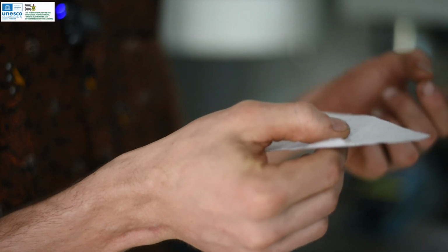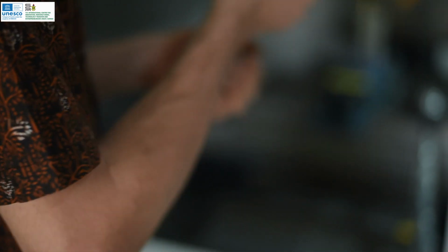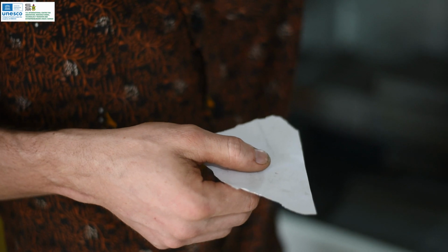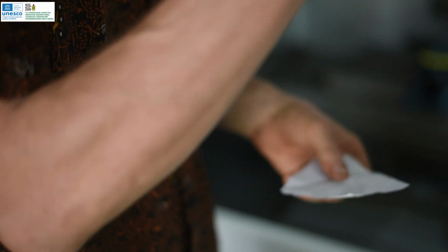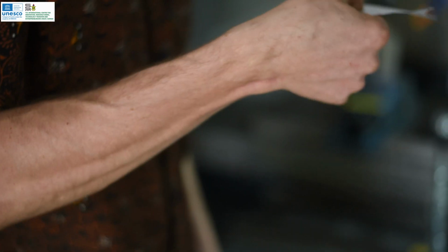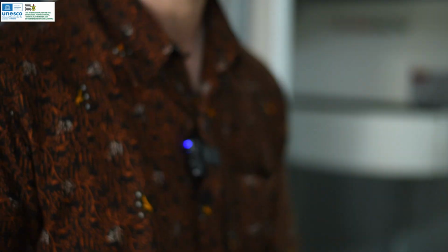Go down until it clamps a 1/10 of a millimeter feeler gauge. Move that until it clamps, and then add 0.01 or 0.1 in that case instead of 0. Whatever you want to be your feeler. Paper is so thin, we call that good enough for what we're doing. If you're working on something ultra accurate, making sure those offsets are perfect, you'll go with something more precise.